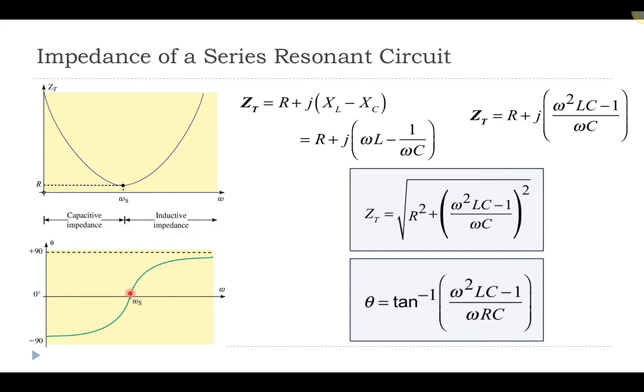And then if we decrease the angular frequency, then the capacitive components are dominating. And so the phase angle should be negative. And that actually naturally comes out from this expression right here. But I think it just makes sense by looking at our picture in terms of which is dominating, because inductive reactance has positive phase angles and capacitive impedance has negative phase angles.